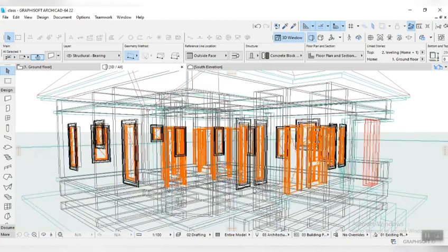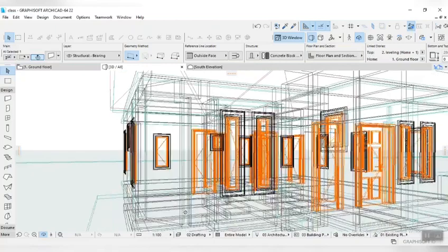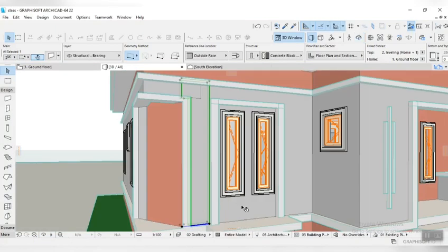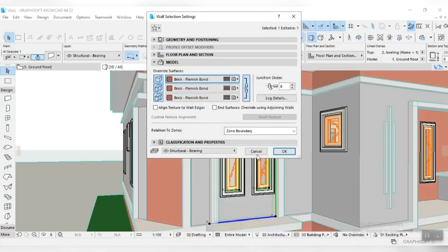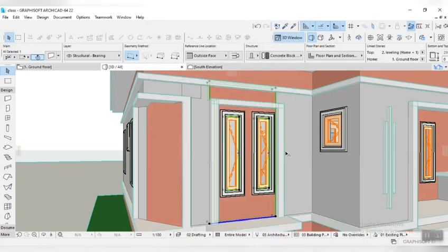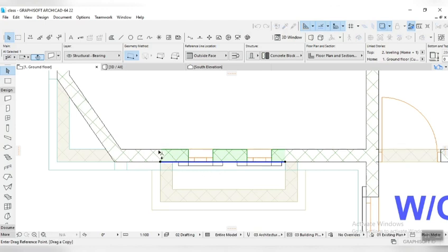So automatically the center is now standing on its own between the windows. It's not a single wall, but check out what's going to happen. Let's go to the wall settings. Let's change this to what we're using. Okay, you see there is an extension up there, so that is why you have to come here. You have to create a copy of this wall.